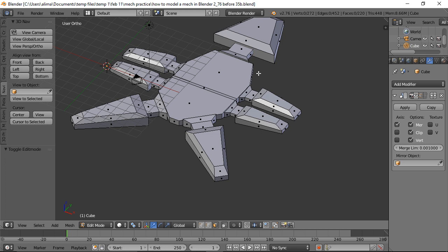Okay, what I'm going to do now is I'm going to hover my mouse here. I'm then going to press C to activate paint select. That circle you see is the area of influence for my paint select. Paint select basically allows you to paint selections. If I roll the mouse wheel one way, the selection will get bigger. If I roll it the other way, the selection will get smaller.